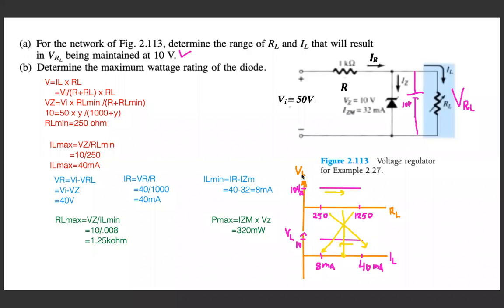these type of numericals you will solve in this particular application of Zener diode. The steps are simple, and if you go step by step, then you will have no confusion. First, calculate the RL minimum, simply dividing VZ by the value, rearranging the variables in this equation. Now divide VZ by the minimum value of load resistance, calculate the maximum value. Now calculate the voltage drop across the resistor. Then the current through the resistor.